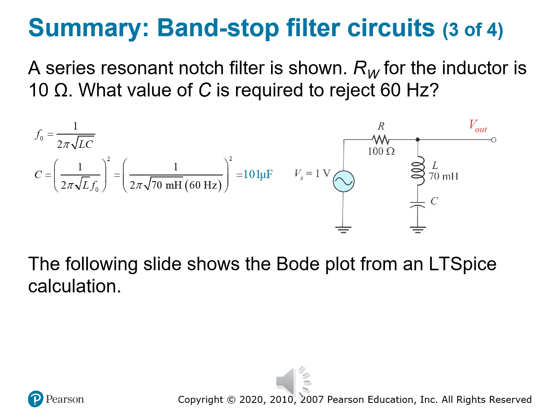And so what does this do? This configuration creates a notch at exactly 60 hertz. That's where the LC combination presents very low impedance. It pulls the frequency down, it diverts it to ground. Think of it like a trap door, where trap doors send something straight to ground. So that's what's happening at this frequency. Everything else flows right past.